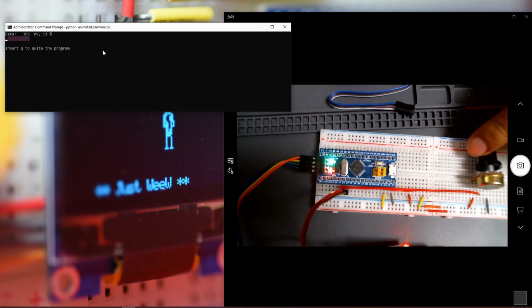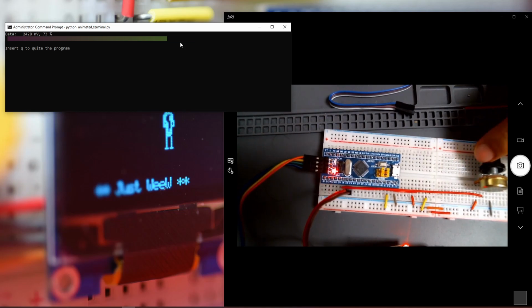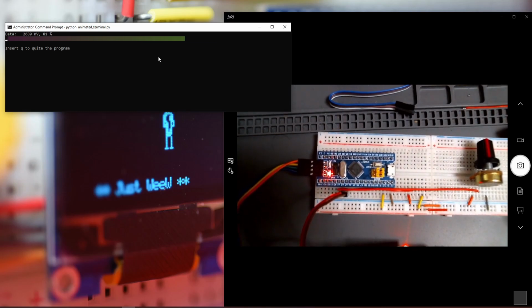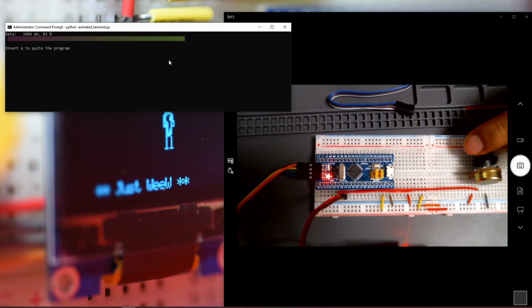So I'll reach this value and then it gets frozen at 400 millivolt, 409, and then it comes back again when it's 2400. Okay, you can see with the LED turning on and turning off how many potential you can. You don't even need to read the value. So this is more if you would like your program doing something at a certain value.